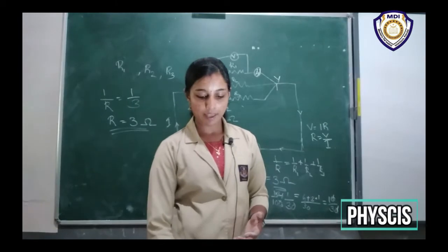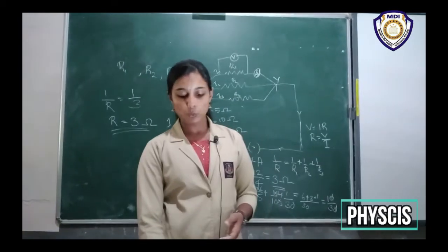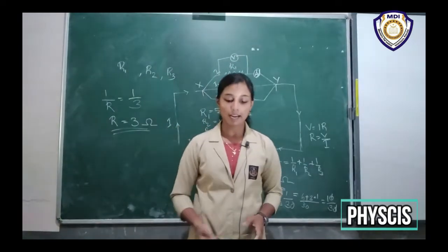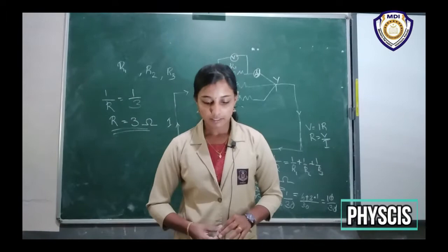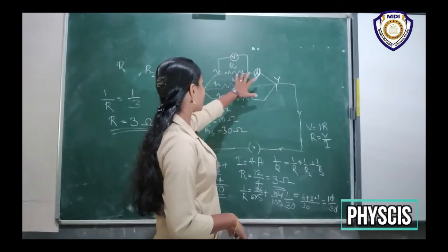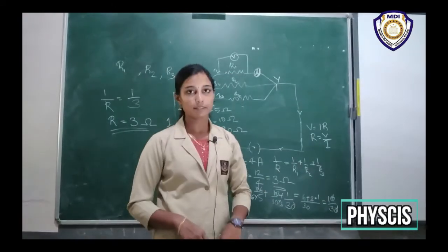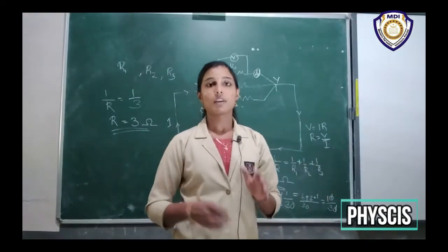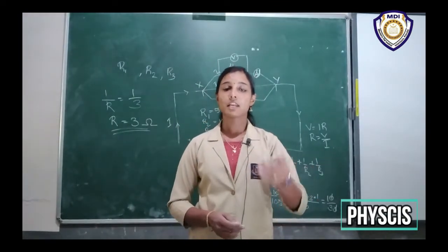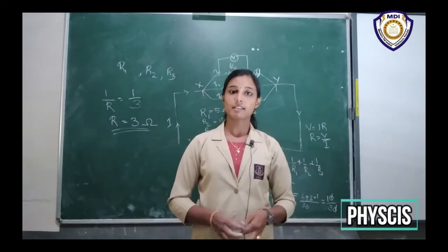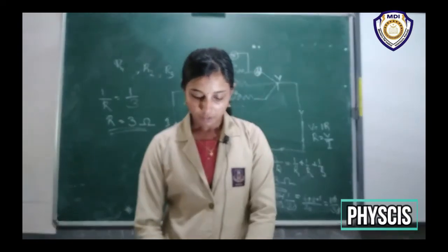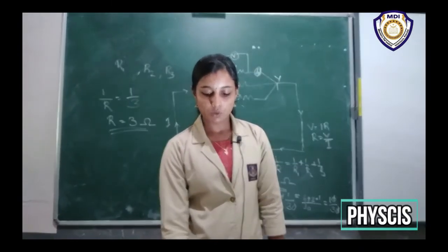On the other hand, a parallel circuit divides the current through the electrical gadgets. So the current passing through these gadgets can be different, right? So we can make use of a parallel connection when connecting the heater and bulb. That means they require different currents, right? So we can fix them in parallel connection. The total resistance in a parallel circuit is decreased.